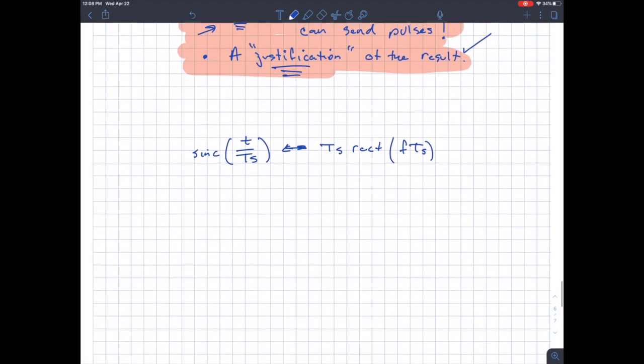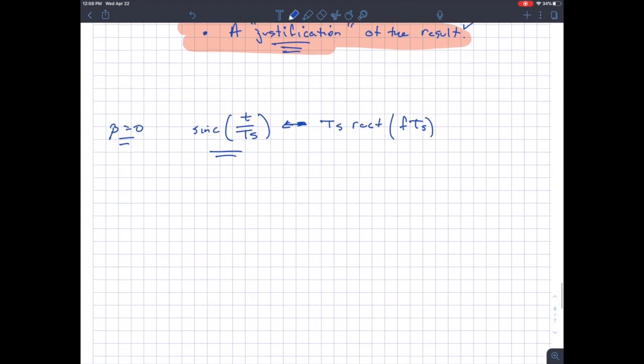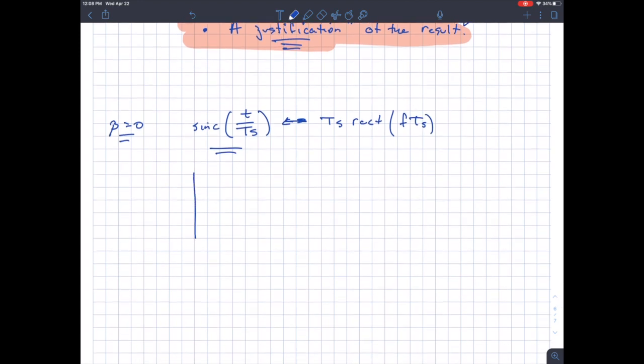All right, so we're going to start with pulses that we're familiar with. This is really a raised cosine pulse with a special case. It's a sinc function. Okay, so if you put beta equals 0 on a raised cosine pulse, you get the sinc function. And so we know what that looks like and why we used it. We used it because it was more efficient from a bandwidth point of view. In fact, it was our most efficient pulse shape that we could use for bandwidth.